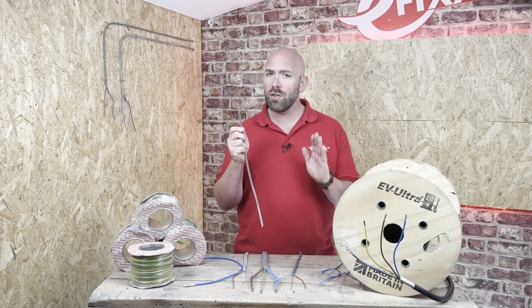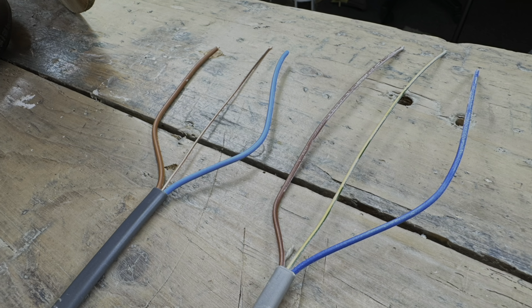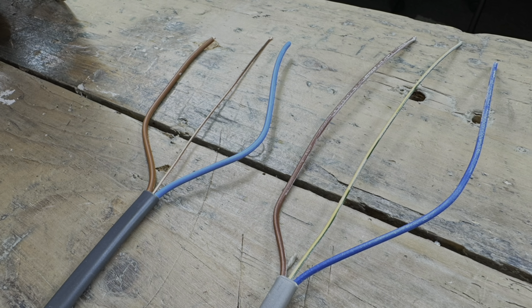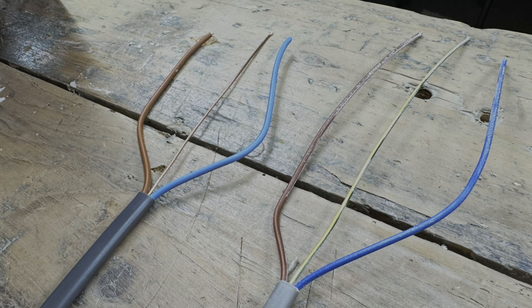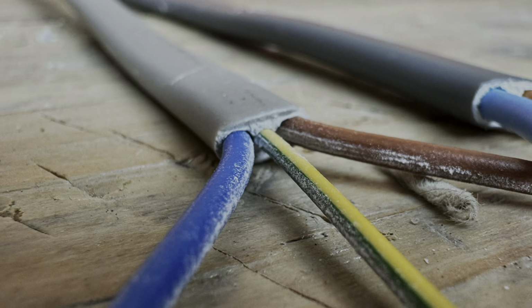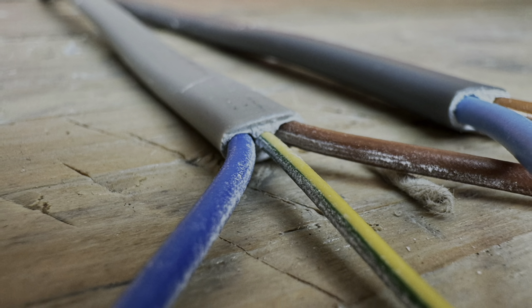This cable, however, does not have a BS number, but it looks exactly the same as this one. Well, that's because this cable is the EarthSure from Doncaster Cables. It's still a 1.5mm cable with a 1mm CPC, but can you spot the difference? If you said that the CPC on the EarthSure is sleeved, then you're right. The cable comes pre-sleeved, but it does not have a British standard number, so does that mean we can't use it?